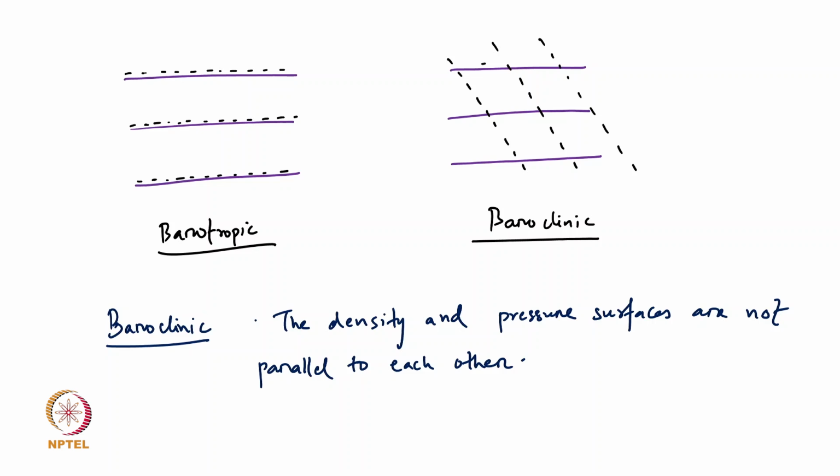So even though away from the boundaries we can assume the flow to be inviscid and incompressible, and only gravity is acting, still, given that density now depends on quantities other than pressure, we will find that the Kelvin circulation theorem does not hold exactly.